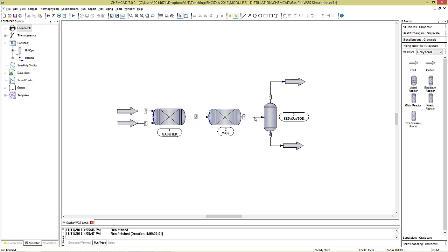Then what you would essentially do here is you would come and look at your H2/CO ratio. As you can see, our carbon monoxide is 6, our hydrogen is 17. This is still way above 2, because if it was 2, our hydrogen was just supposed to be around 12 point something, 12.4, because there we have 6.2.